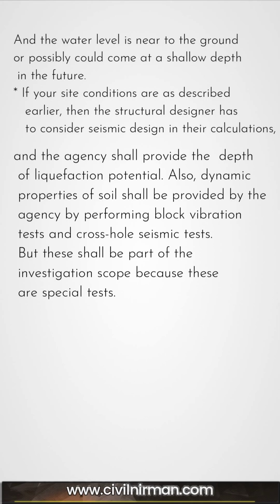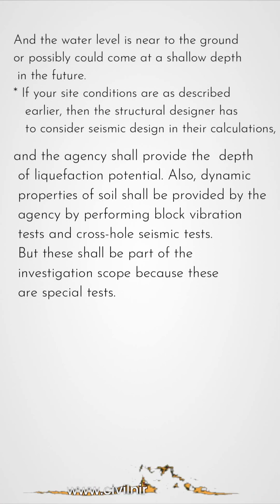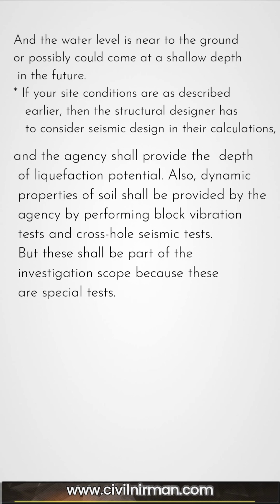If your site conditions are as described earlier, then the structural engineer has to consider the seismic design in their calculations and the agency shall provide the depth of liquefaction potential. Also, the dynamic properties of the soil shall be provided by the agency by performing block vibration tests and cross-hole seismic tests. But this shall be part of the investigation scope because these are special tests.